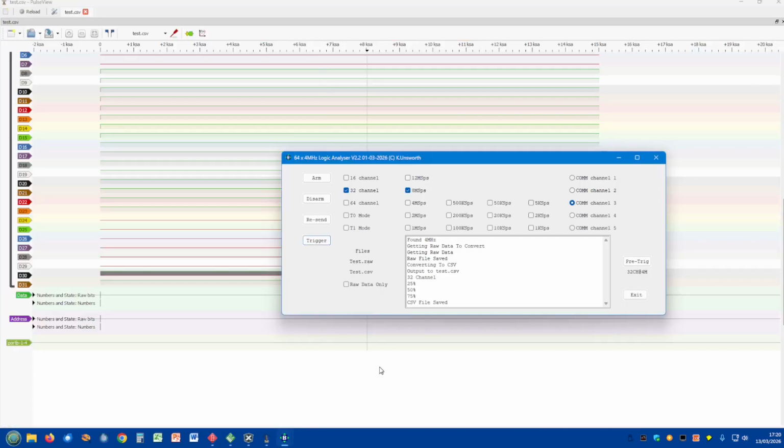What I'll attempt to do now is, I've got channel 31 connected to A15, and often when it crashes it tries to read further up the memory. So if we put on a pre-trigger, if it tries to read in the top half of memory, it will trigger and grab the data. Sometimes that happens shortly after a crash, and that's how I managed to see what's going on just before it crashes. So we're scanning at the moment and just waiting for it to fall over.